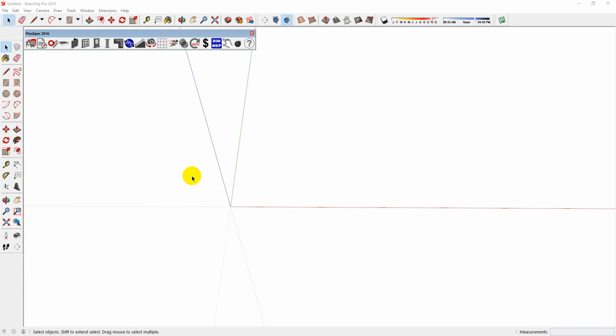Plusspec uses the SketchUp environment, so it's important that you understand the axes, which are represented with the blue, green, and red guidelines. When drawing with Plusspec, you only ever have to worry about the green and red axes. By sticking to these axes as guides, you will ensure that you will always draw at right angles.